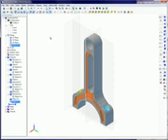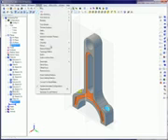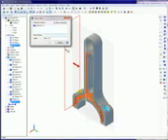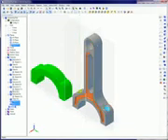The scale or mirror part feature is a global feature that makes an entire part bigger or smaller. As a global feature, it affects everything above it in the Design Explorer. Note, there is a separate feature mirror tool which is different, making mirror copies of features, leaving the original features unmodified, much like the sketch mirror feature.